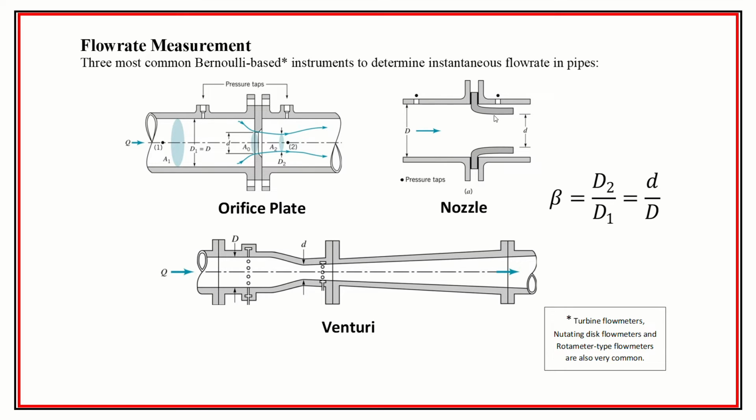We also have a nozzle. So this is sort of a smoother transition. It's not quite the severe blockage that an orifice is, but it makes this nozzle right here, and the pressure taps that we have off of this are at particular locations away from here. And from this, we can find from the pressure drop, and including some calibration information, some correction factors on top of this, we're able to estimate what the flow is.